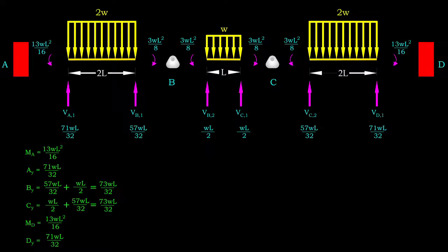With the calculated shear forces, we can calculate the vertical support reactions by summing the shear forces at respective locations. The moment reaction at fixed ends is equal to the internal moment at those points. Again, the beam is symmetrical and therefore, we should obtain symmetrical reaction forces as well.